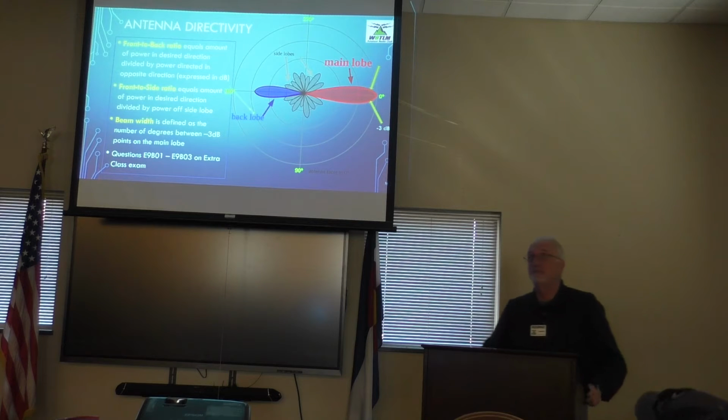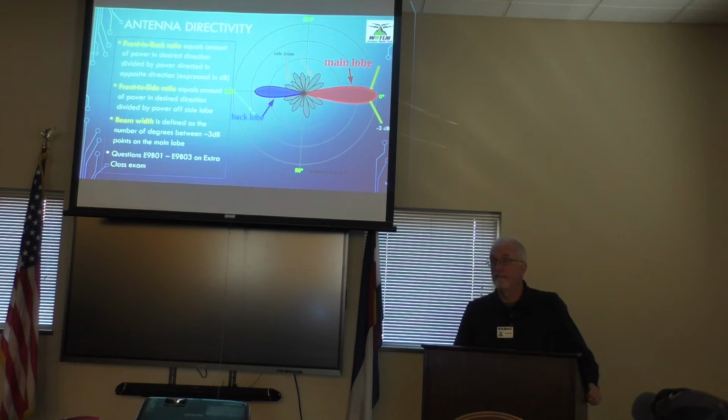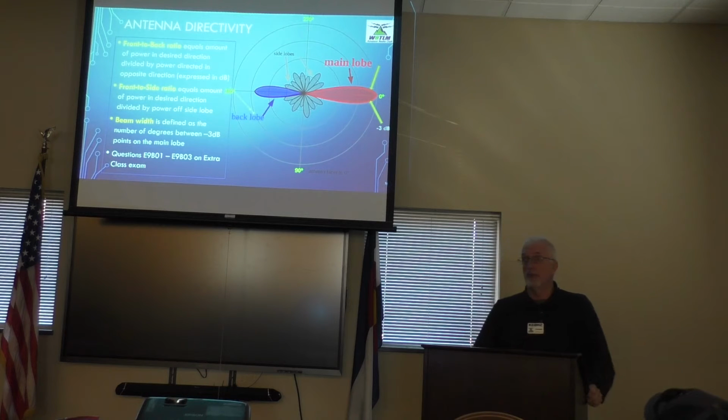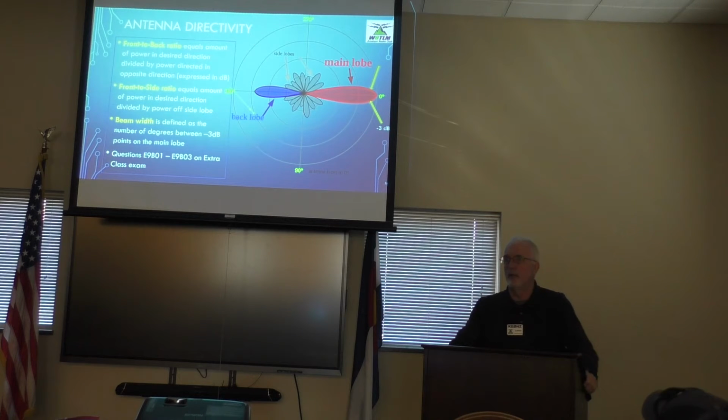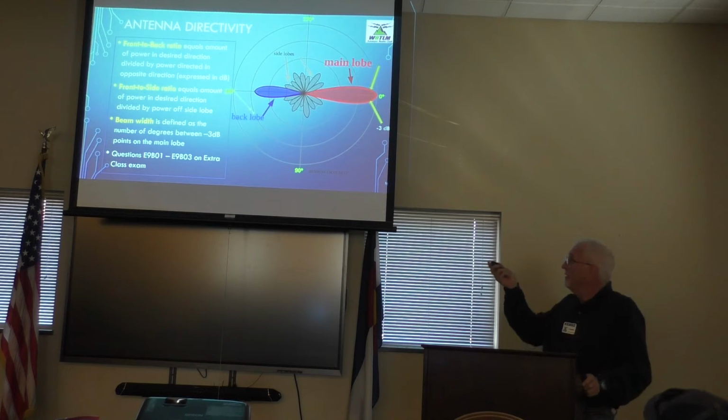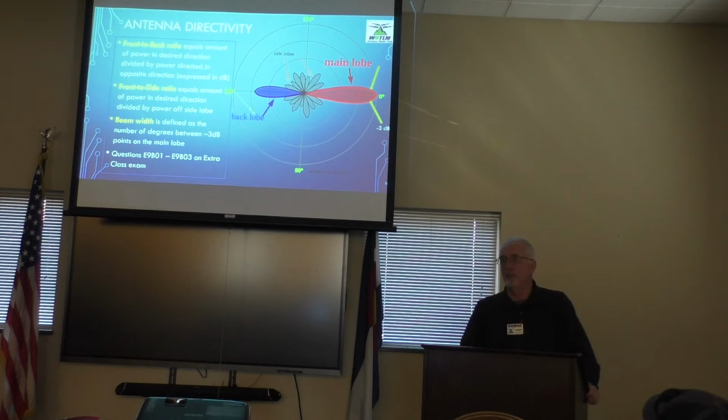Any other questions? Yes. I'm not clear yet about that. Is it still directional? Oh, yeah, definitely so. I didn't cover any of that, but you can find charts for it. When you're looking at this, you're going to look at these terms: front to back ratio, front to side ratio, and the beam width. And the beam width on that is going to be fairly important. I can't tell you what it is in an antenna like that off the top of my head. Well, that's why you have to point the antenna toward the transmitter for channel 13. Exactly.